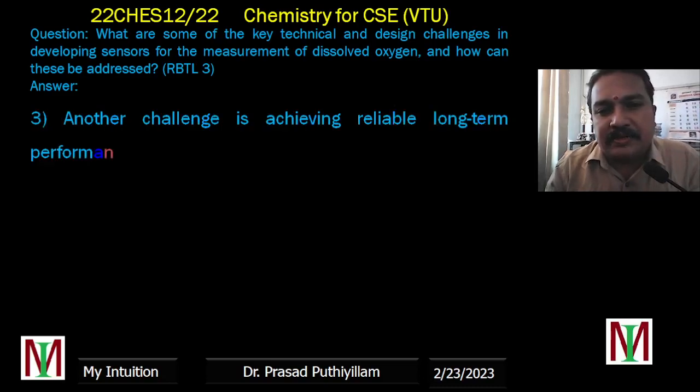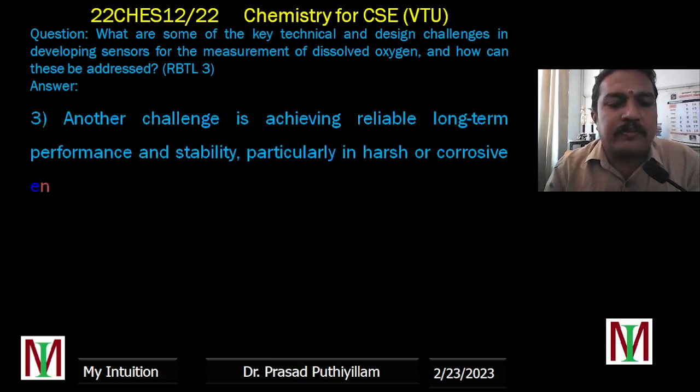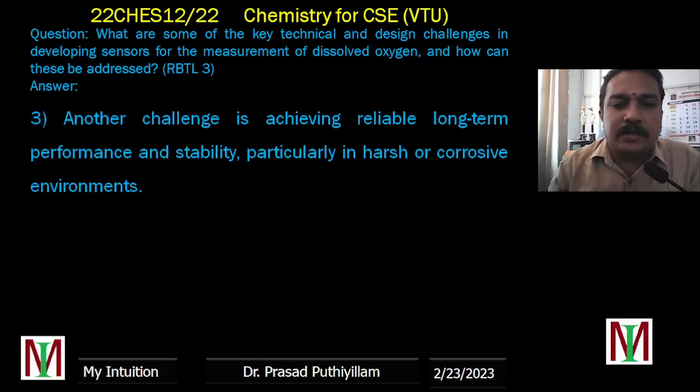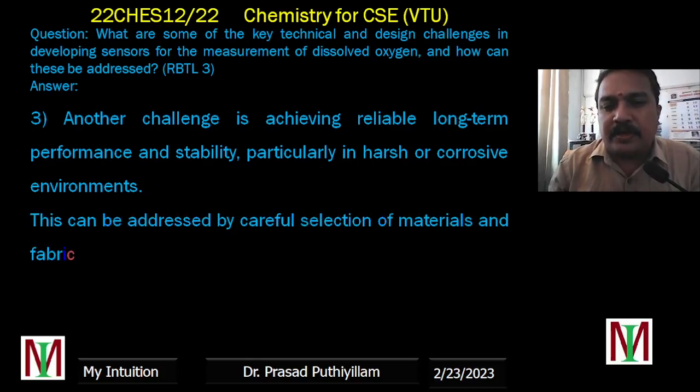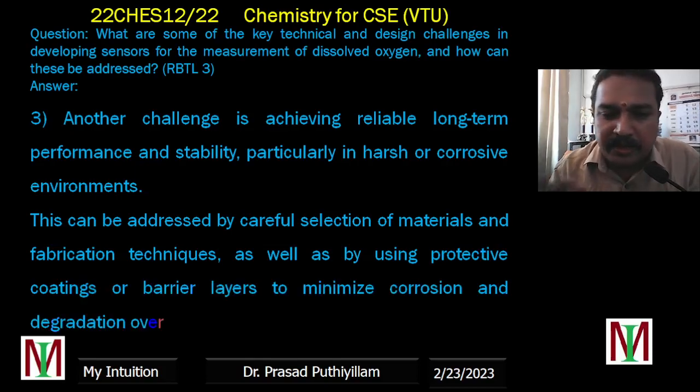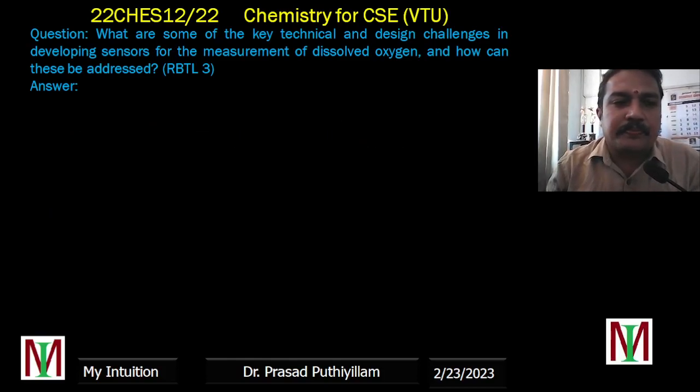Another challenge is achieving reliable long-term performance and stability, particularly in harsh or corrosive environments, in which we have to continuously measure the dissolved oxygen content. This can be addressed by careful selection of material and fabrication technique, as well as giving a protective coating or barrier layer to minimize corrosion and degradation over time.